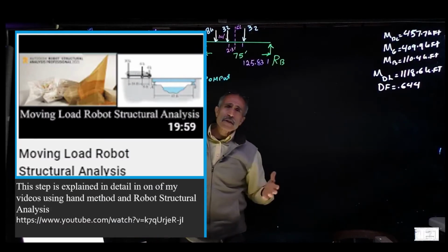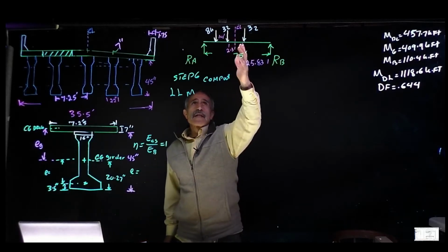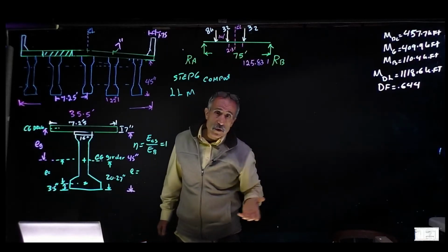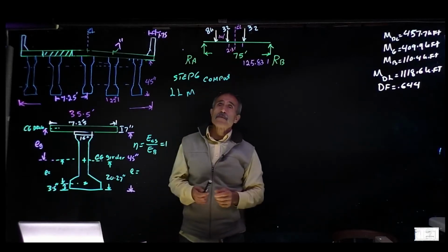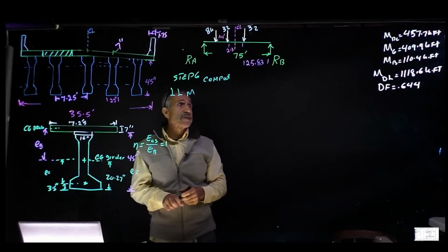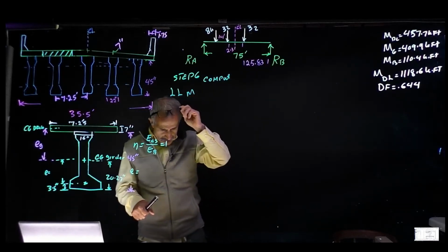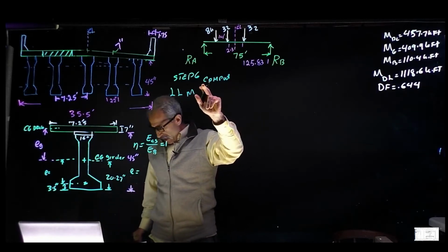A lot of times in a lot of books, they make a calculation and just put this at the center line. They don't bother with that, but it comes out very close. So we know that's very close. So let's go ahead. Before we calculate the maximum moment, we're going to calculate the reaction forces for this type of load. I'm going to take a moment about point A, which is right here.